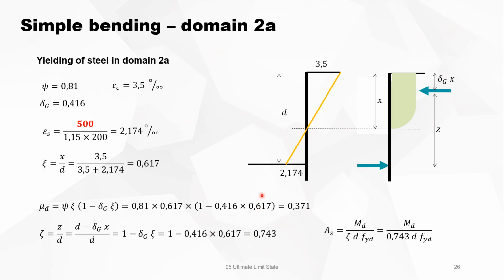It is of great importance that you should always work on the left-hand side of this diagram. Why? Because you want the steel to be yielding. You do not want to work with steel which is not yielding. It's a waste of money.